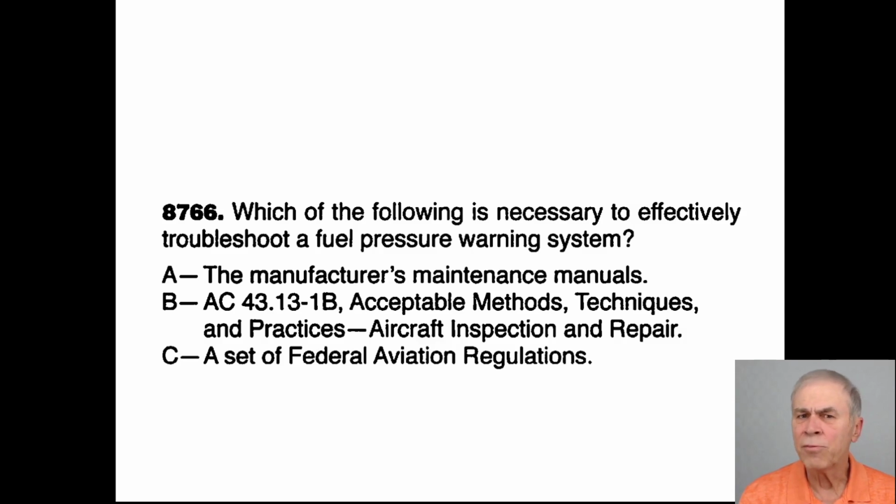But it's not specific enough to tell you the specific pressure that's going to be developed for the fuel pressure warning system of that aircraft. Or C, a set of FARs. And you may get the requirement that you are to measure fuel pressure, but you are certainly not going to get told what the fuel pressure is.